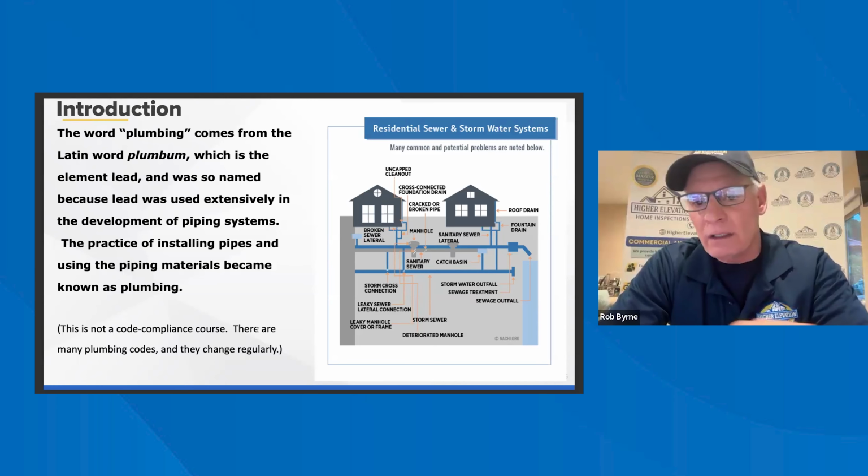So when you have the backflow preventers, when you didn't have them, the water would be able to move within the water main. Now that you've got these backflow preventers and all that other stuff, you're kind of isolating the system. So if it gets overpressurized or backs up, it has to go somewhere. That's the idea of the expansion tank, because you can compress air, you can't compress water.